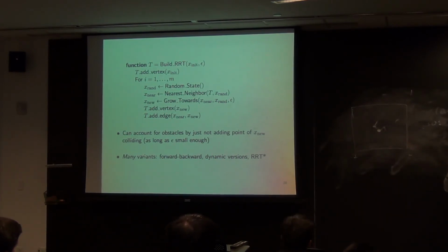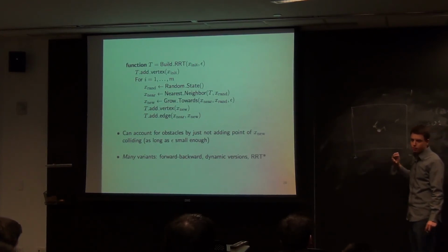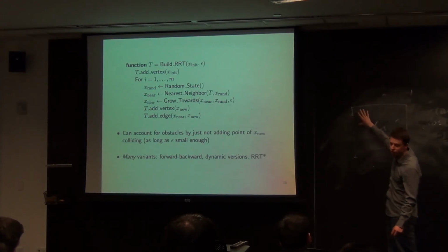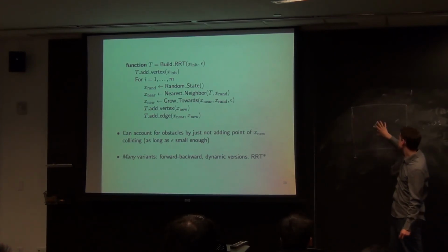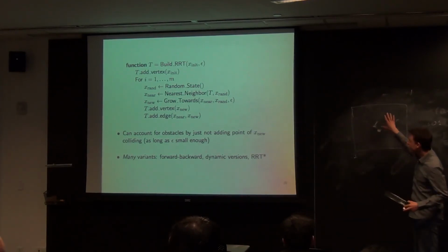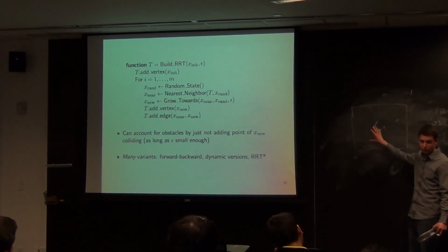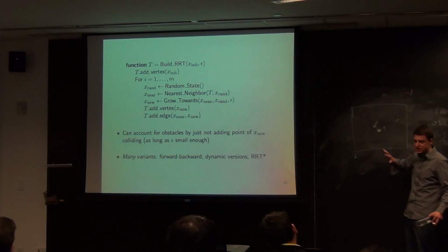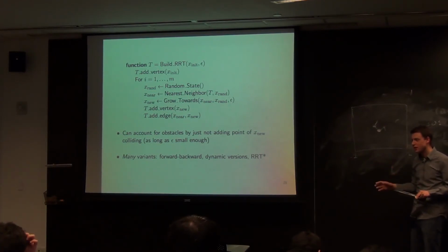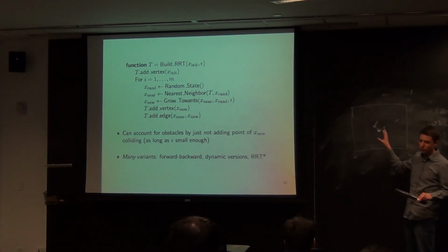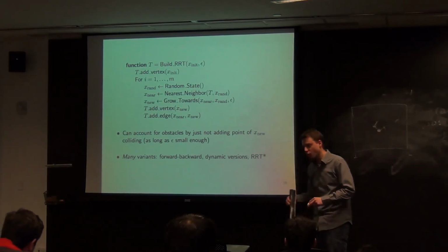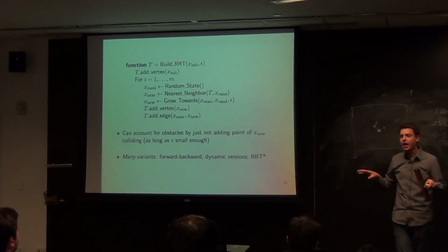And what's very cool here is that because we are sampling randomly, we're more likely to sample areas where we have big areas with no tree in them. That was imprecise, what I was saying there. But basically, when we start off, there's a lot of empty space, right? And we're more likely to sample in that empty space than in the space we've already sampled before. So that means we're more likely to grow the tree outwards into the space where we haven't sampled yet. And this process repeats, and it's actually provable that what it's doing is sampling, I think, weighted by the Voronoi diagram of all these points we have so far. So if you've seen that before, then that might make sense, but otherwise don't worry about it. But essentially what this means is that we are going to grow this tree very quickly into areas where we have not had any samples before.